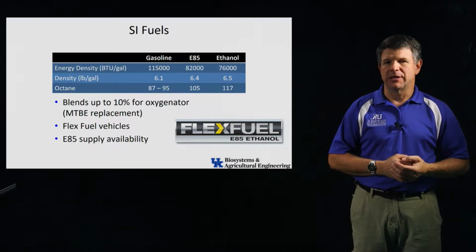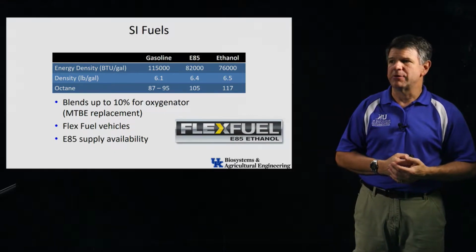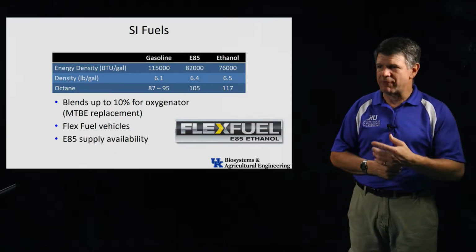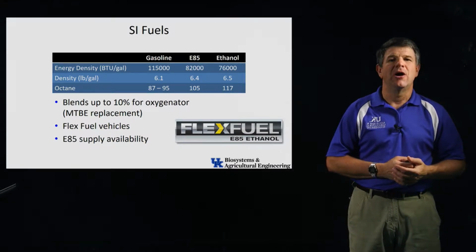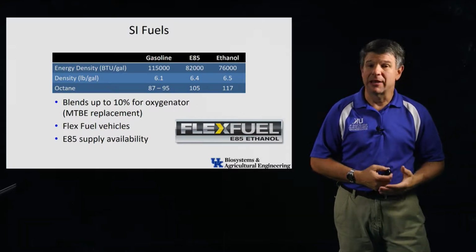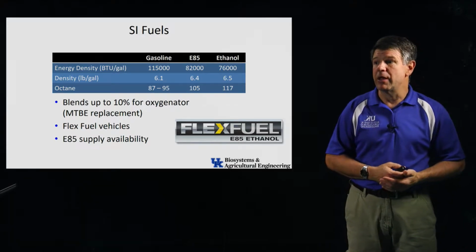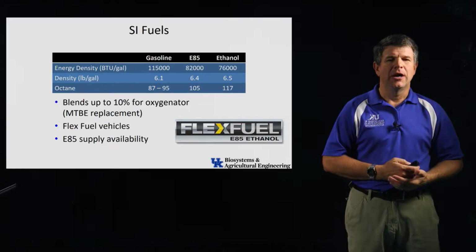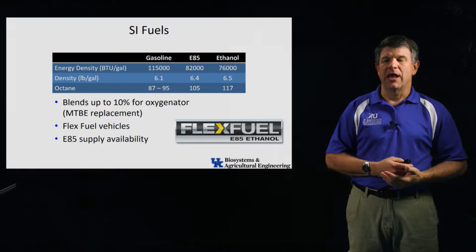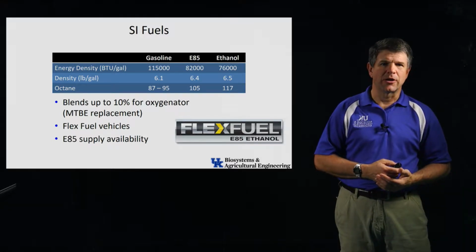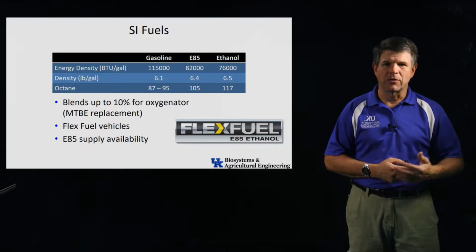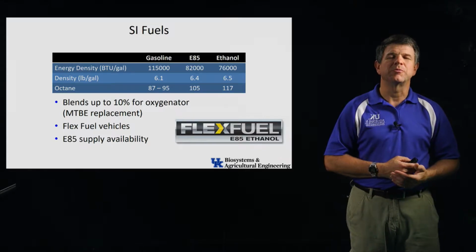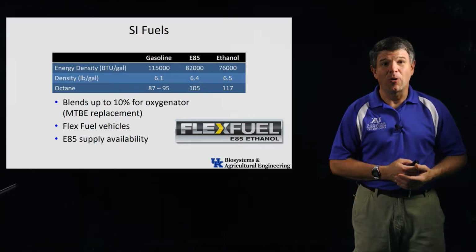Almost all of our fuel is an ethanol blend, about 10% typically. And most of our vehicles now are flex fuel vehicles, and you see that flex fuel symbol or something similar on a lot of vehicles. That tells me that, hey, that vehicle could burn ethanol if it wanted to, up to 85%. So we do have some E85 supplies. It's not widely available, but in the United States, we do have E85 available at some pumps. Now you go to other countries, and this becomes more critical. I traveled quite a bit to Brazil a number of years ago, and their gas stations down there are a whole lot more complicated than ours.